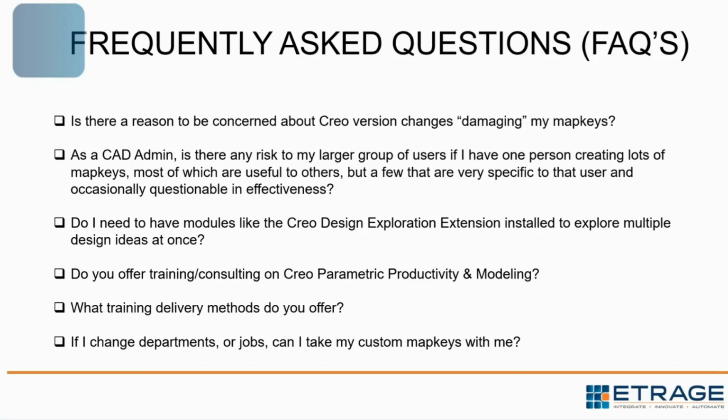And so for an individual user, it doesn't matter if Paul has his own specific quirky set of map keys that he likes to use. An admin file will still come in. Creo will pull that plus Paul's additional customizations and use that to run Paul's session. But any other designer that's not Paul, I just made up a name, can still run the full admin set without any Paul-specific customizations, right? And so you can have the best of both worlds. Essentially, that's what I'm trying to get at there.